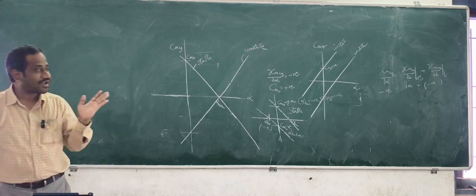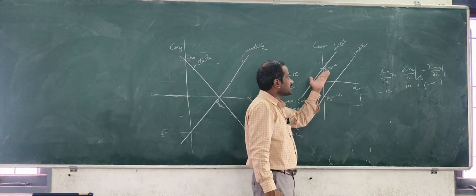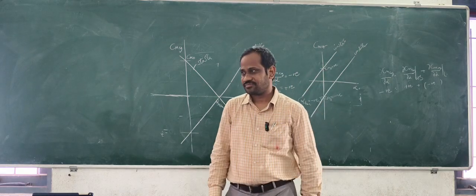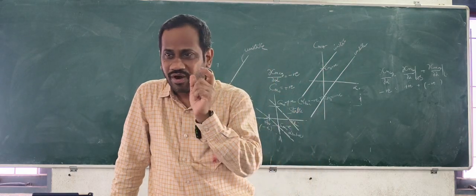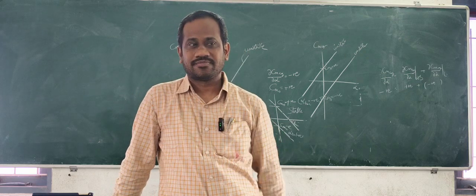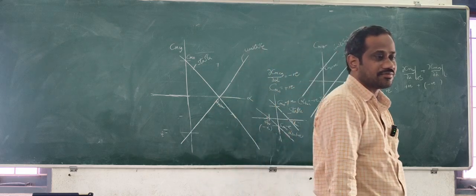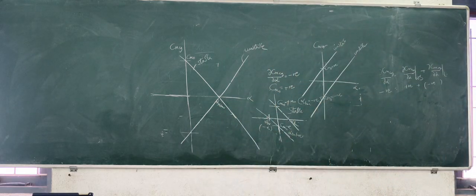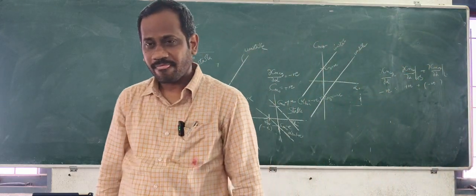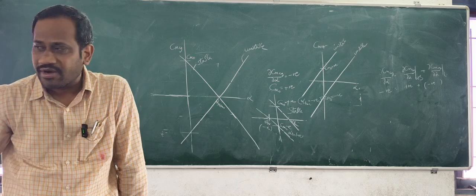So this particular aeroplane will always try to look for the equilibrium angle of attack as positive, but it is primarily not a stable aeroplane. So Cm naught positive, what type of criteria is it? Cm naught positive is a balanced criteria. Whether the aeroplane is balanced at a positive angle of attack will be decided only by Cm naught, negative or positive? Positive. So can someone consolidate this? These two. This is an important discussion.